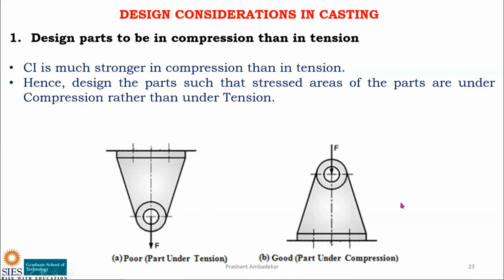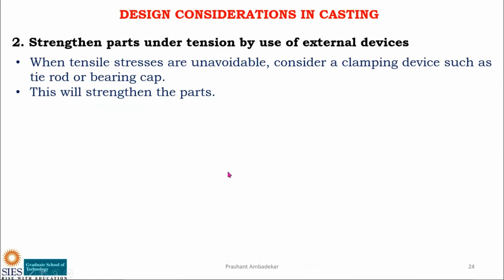Okay, so depending on how you want it, this force could have been in the upward direction, or the force could have acted in upward, this from here in the downward direction. Okay, so instead of designing the part to be in tension, now this part is in tension and this part is in compression. Okay, if the sole purpose is that the entire part should remain in compression rather than in tension.